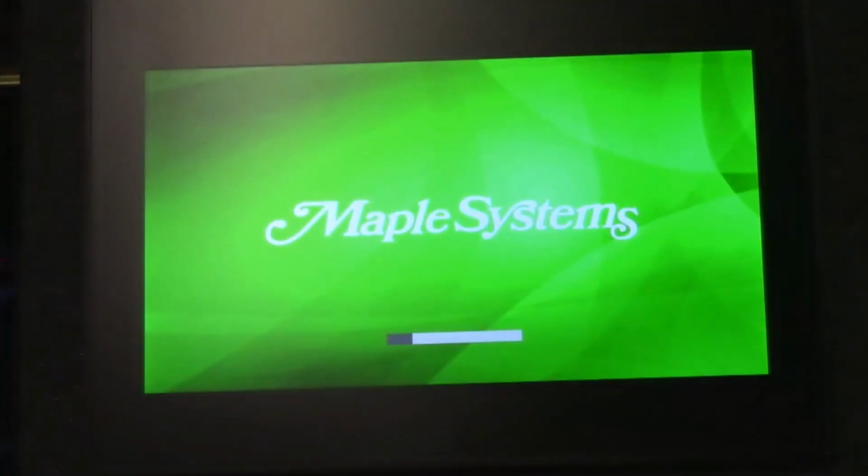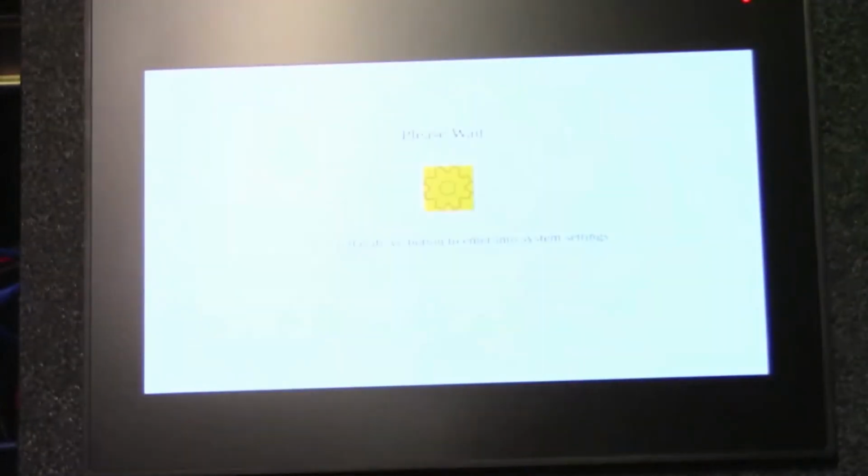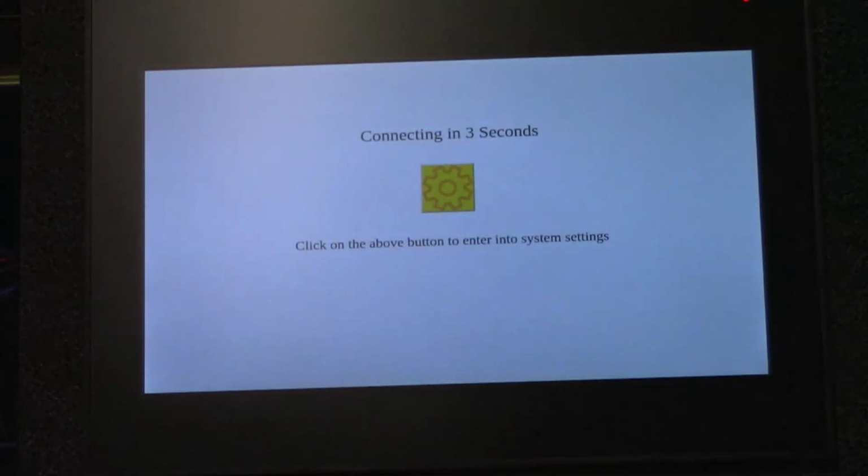Again, something to keep in mind while this is booting up, these Web HMIs are Class 1 Div 2. So they are perfect for any industrial automation facility that requires that classification. Again, as I mentioned a few times, they are high brightness, sunlight readable, so great for any outdoor application. The capacitive screens are PCAP, so they can be used with light gloves, and then our resistive models can be used with heavier gloves for more rugged environments. So something to keep in mind there when evaluating these units.